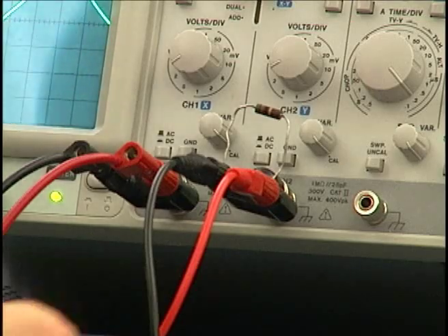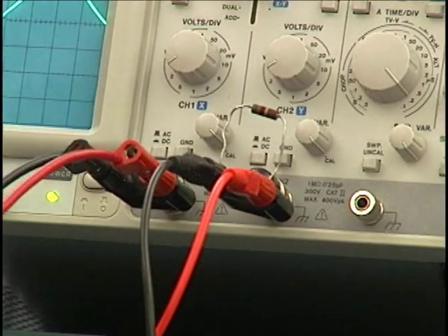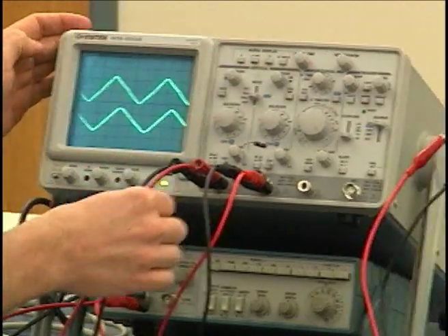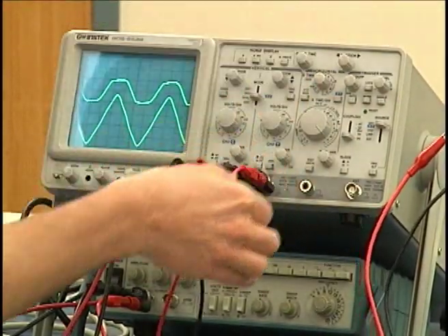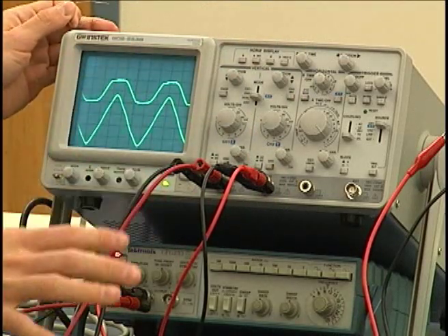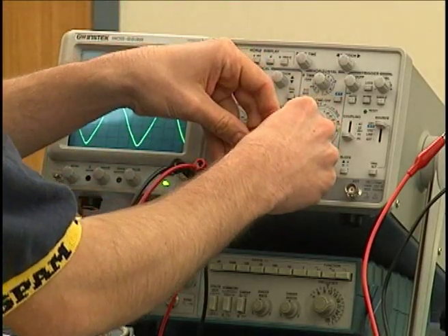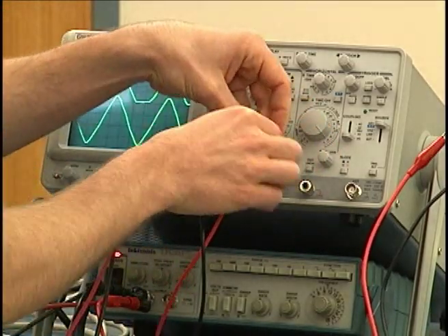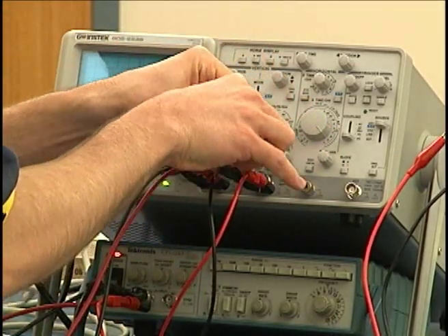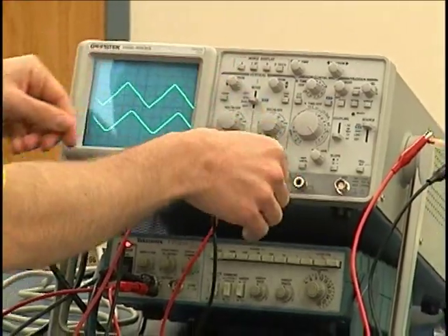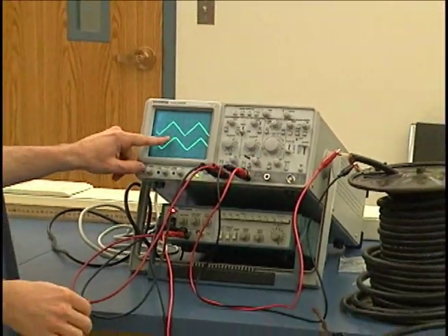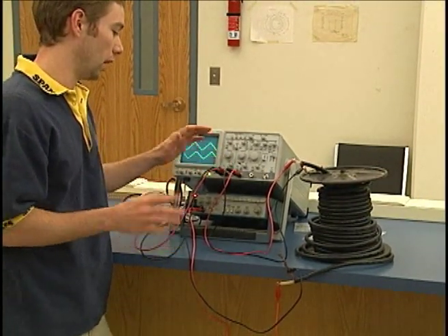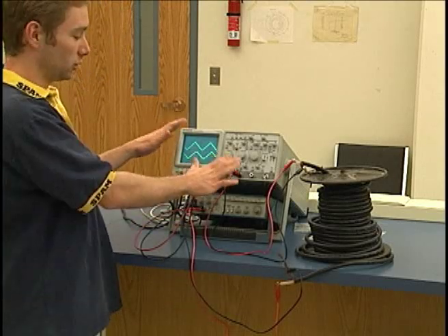So if I take this out, well, okay, first here is just channel 1, just the initial signal coming through. Now if I change my oscilloscope to show both of these things and I take out this resistor, you'll notice the waveform gets really distorted and it looks all garbagey. That's from some factors which we won't go into here in this particular lab. So I'm just going to put it back in there, make sure it's nice and snug, so that our waves look more or less triangular-ish. They will be a little bit off because this resistor won't exactly match up the resistance that we need to offset the impedance imbalance, but this will be good enough for our purposes.